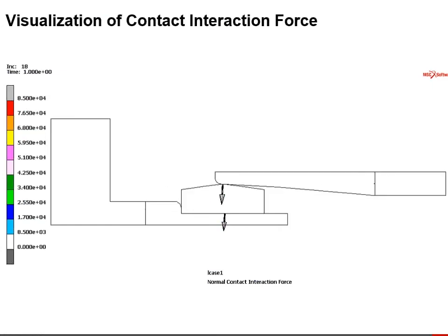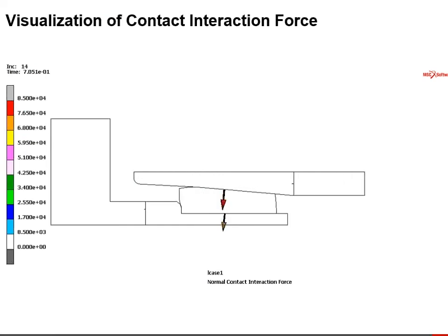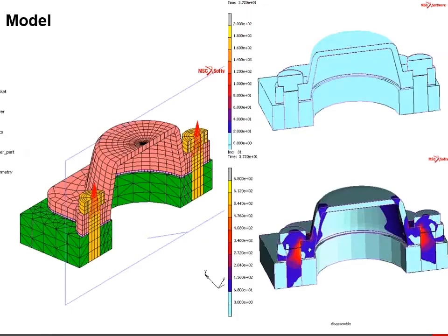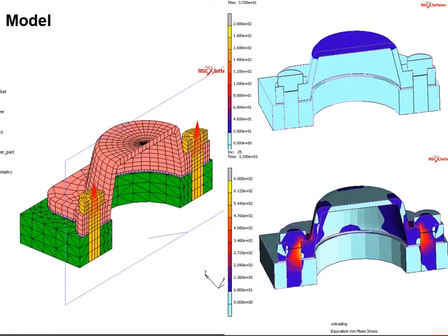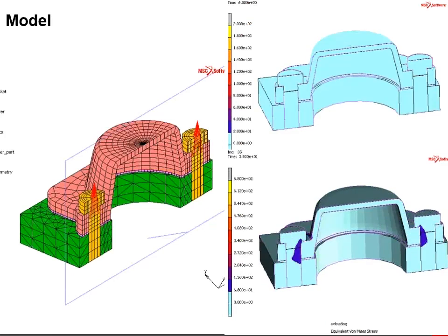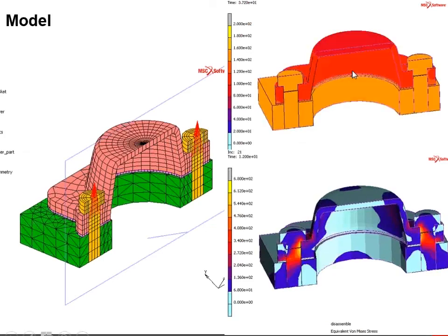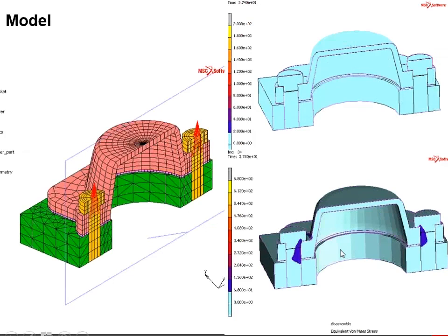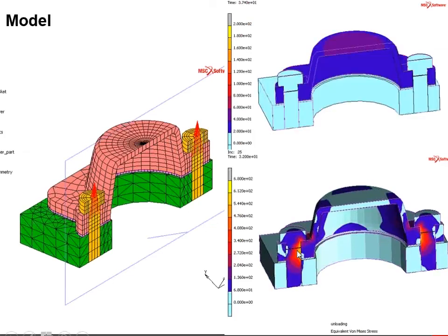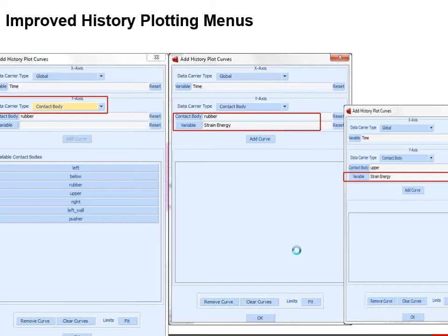This is also a very nice tool to look at free body diagrams of bodies in your structure. Normally, of course, we typically took a look at the model. This is our favorite manifold model, testing the gasket element, and we might have looked at the temperatures during that process or the stresses, and particularly the stresses in the bolts. But now what we can do is we can use this capability for doing time history plots where we don't look at the total behavior, but we look at the interaction behavior between bodies.